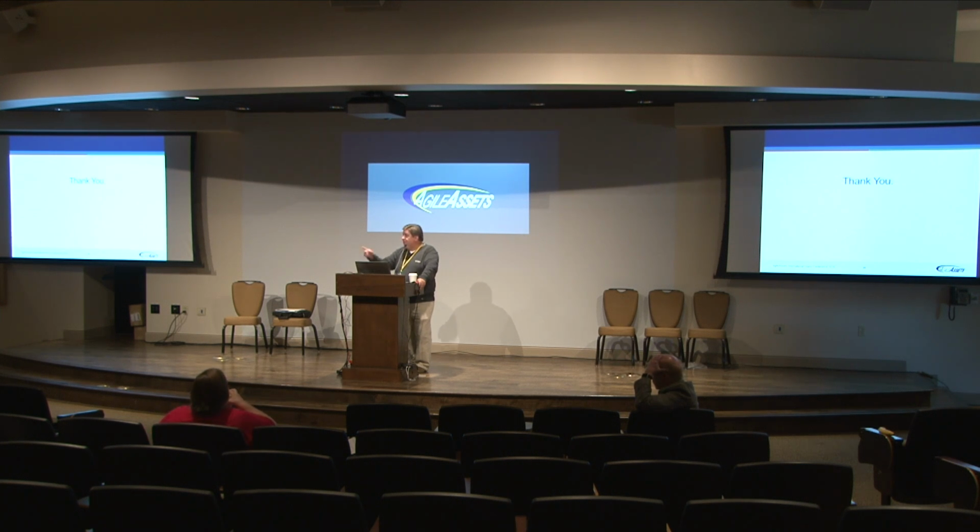It is pretty important to do the editing through Roads and Highways because it does this edit log, and that's what powers these web services. One of the things we tell it is that every time you run the interface, we timestamp that, and the next time we run it, we say, give us all the changes from the last time we ran it till now. That edit log has those timestamps of what all happened between those two dates. So it's important to do it through the software so that it gets processed right.